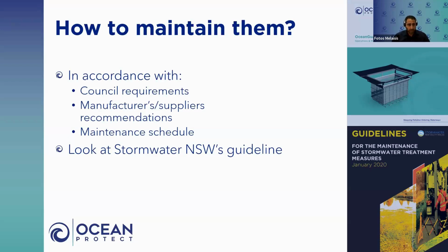If you split it up into ongoing inspection versus comprehensive cleaning, well, then you might be able to just assess the actual sediment accumulation in the bottom of the sump, a visual assessment of any floatables on the surface layer, that kind of oil sheen that sometimes we see due to hydrocarbons can also be noted. And then there's the full vacuum truck type induction, where the entire volume of water and sediment is removed from the chamber. And in some cases, there's also some sort of cleaning behind the screens or actual high pressure washing of the screens to basically bring those back up to a high performing standard.